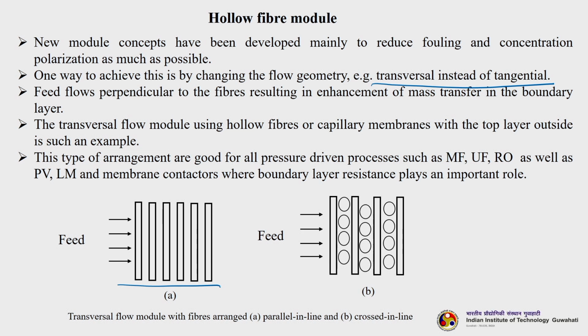This type of arrangement is good for all pressure driven processes, whether it is microfiltration, ultrafiltration, RO process, as well as pervaporation and in liquid membranes also, and especially membrane contactors where boundary layer resistance plays an important role. In many membrane systems, the boundary layer resistance plays an important role. Wherever it is anticipated to play a greater role, because then it will provide more resistance to flow, your separation will be drastically reduced.